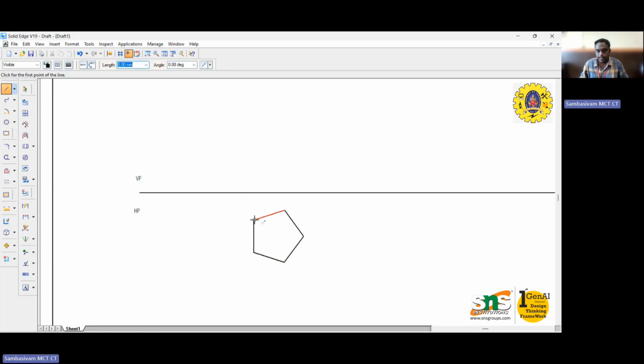As I said earlier, the diagonal surface has to be drawn like this with the midpoint. Similarly, from this point to this point, I have drawn the midpoint. Similarly, from this point, I have drawn this midpoint right now. So using the trim option, I would like to remove the excess lines, which means the joint has become a single part, and similarly, I would like to join the surfaces from this point to this point. This is the simplest way of projecting a pyramid.